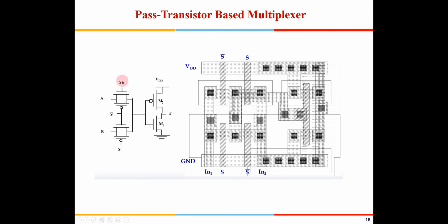Here I am using only S. Suppose I have 4 transistors and I have signals S0 and S1. One of them needs to be selected, so I use a decoder there. Yeah, it is wired OR. For all multiplexers it will be wired OR.